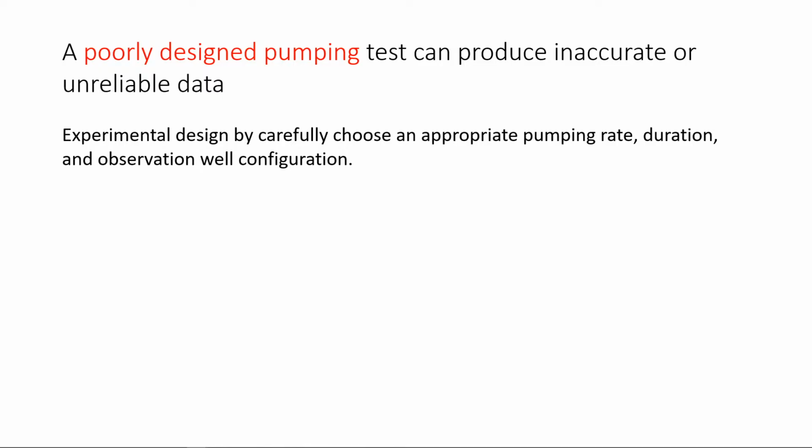Well configuration could also involve inaccurate well screening or casing placement. The placement of the well screen or the casing is important, because if you are placing the casing in a portion of the aquifer that's clay, you will not be able to conduct a pumping test, since you have very low hydraulic conductivity.